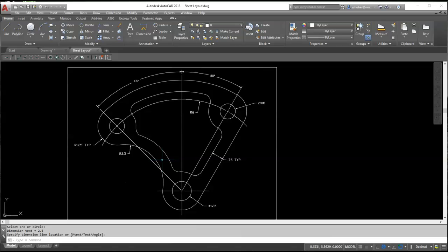Alright, I'm going to do one last thing. Instead of making you guys put dashes in here and create all these random dashes, I'm going to introduce something you need to follow. So we're going to make this a center line. So what I'm going to have you do with these longer lines that are center lines and we want dashes put in, I want you to direct your attention up here where the properties is at, up on the ribbon. The last one is line type.